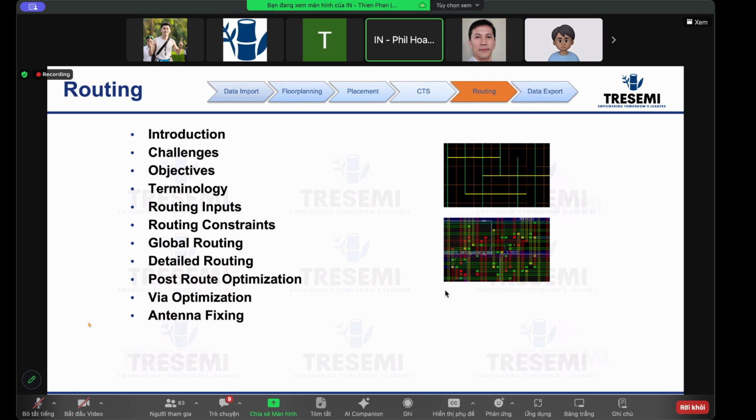So when you look at timing, you're using a wire load model, as was said. When you look at timing, everything, so the synthesis, place and route, meaning floor planning, placement, CTS, routing, everything will have the same timing models. What are those? Those are the .lib, right?